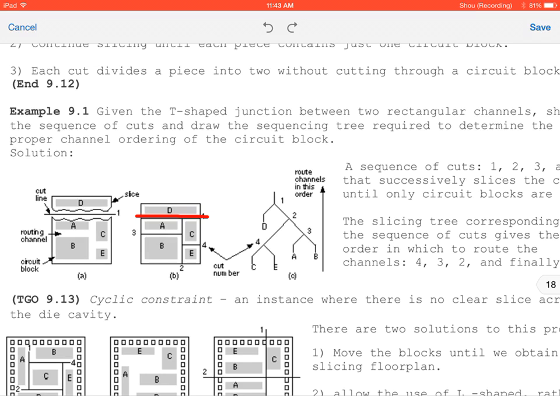Okay? So then, from this cut, we're trying to figure out what's our most effective cut. Can we get all the way to an edge? Here we can. So the next thing we're going to do is go this way, right? So this becomes our first cut, and then we make our second cut. With this first cut, we can access D, right? The whole goal is that we want to be able to access every possible cell. And hopefully this min-cut will show you why having different layouts, even with the same logic, can contribute to more wiring.